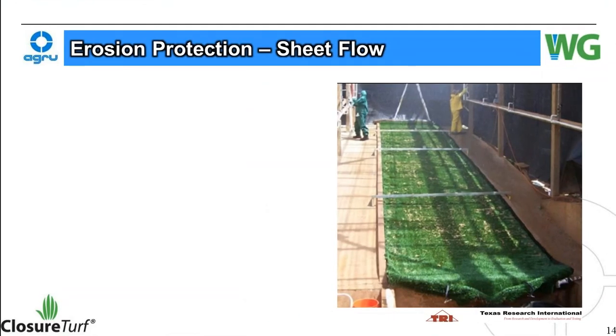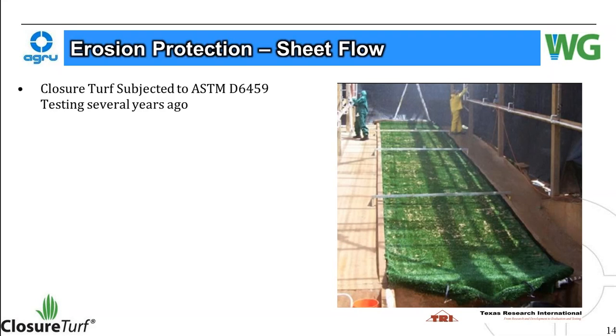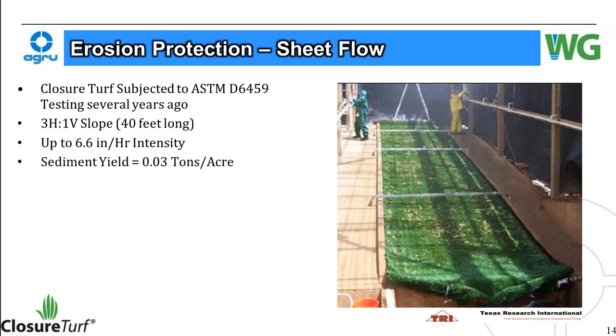Next, erosion sheet protection, where ClosureTurf was subjected to sheet flow testing several years ago using this ASTM method. It was a 3-to-1 slope, 40 feet long, and was up to 6.6 inches per hour in intensity.